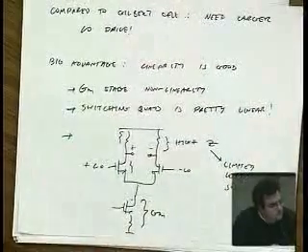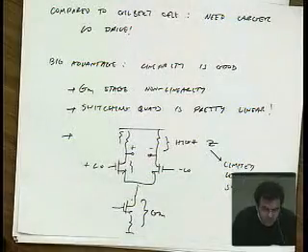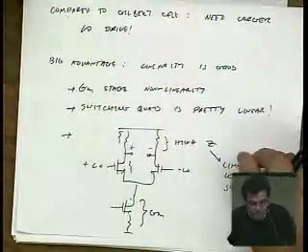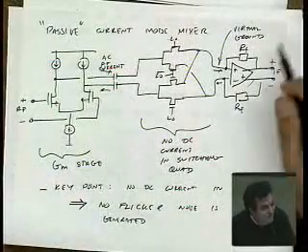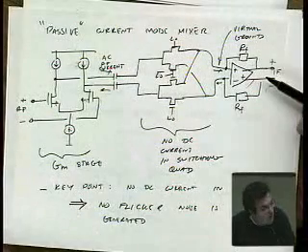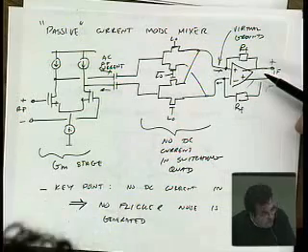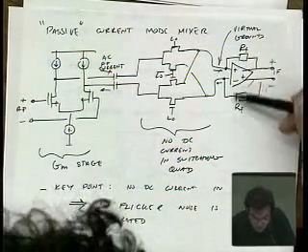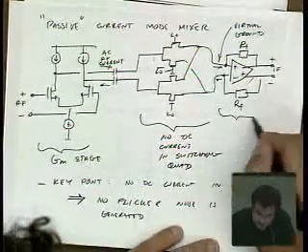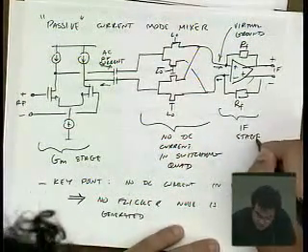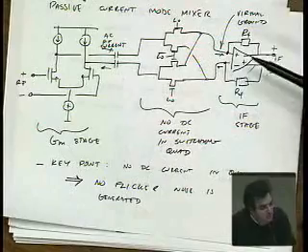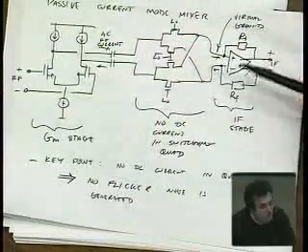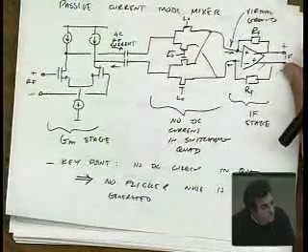Yes? What about the op-amp that you had on the final stage? Yeah, you kind of moved the problem to the op-amp. But remember, in theory, you can build a rail-to-rail op-amp, right? So you've basically moved the issue of voltage swing to the op-amp. If you have a multi-chip solution, you could also potentially run the op-amp on a higher voltage. Because remember, this is an IF stage, so you could use longer channel length devices, thick oxide devices, run this off a higher supply voltage, maybe 5 volts. Maybe this here works with 3 volts. And you can even get more performance out of that. Okay, so it somehow decouples the problem.